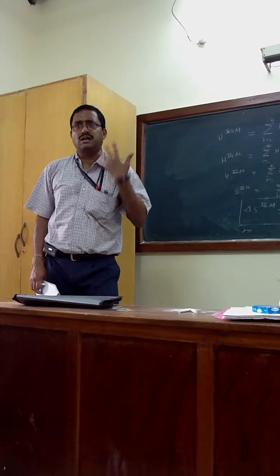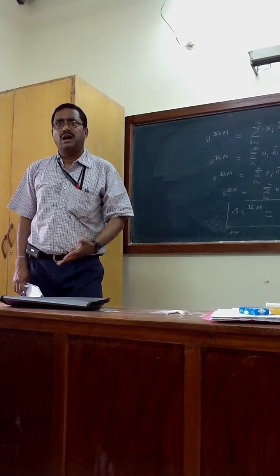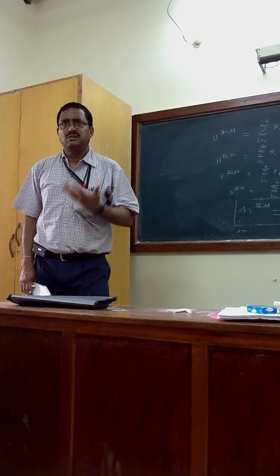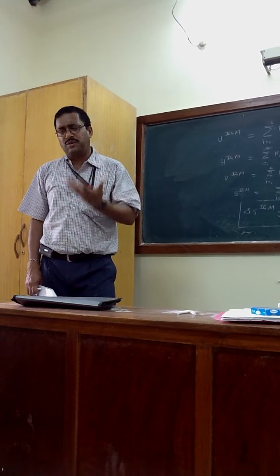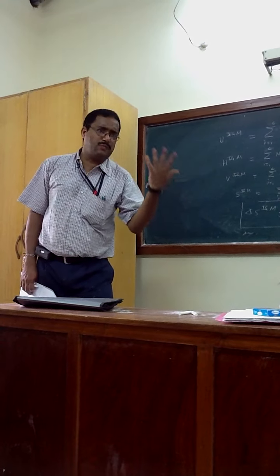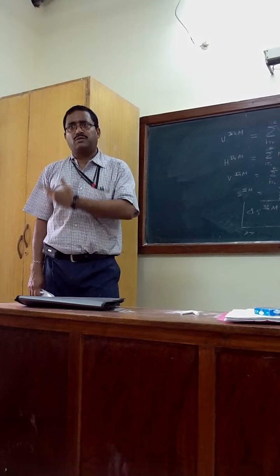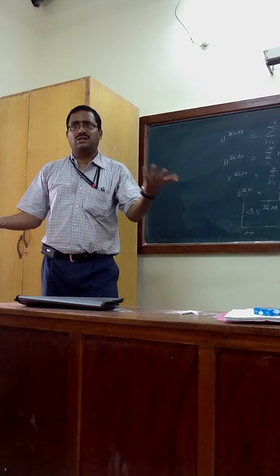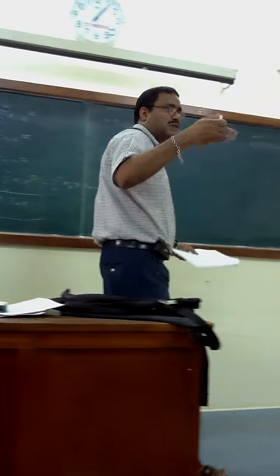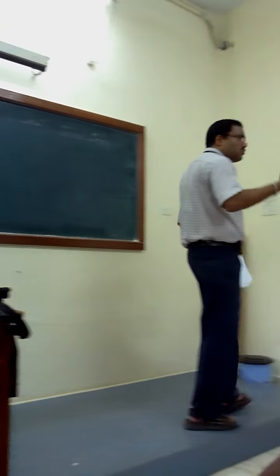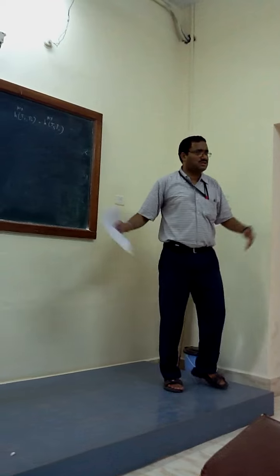Humid air has the components water and bone dry air, two components. When we talk about the enthalpy, we don't say this is the enthalpy for bone dry air and this is the enthalpy for water. We talk about humid air enthalpy. That's why we talk about the mixture. We won't go for the individual property. The same way you can calculate.